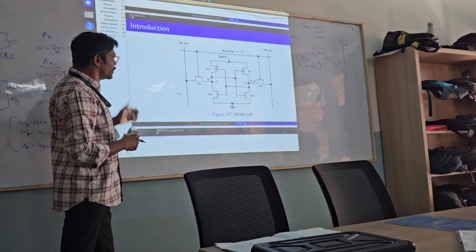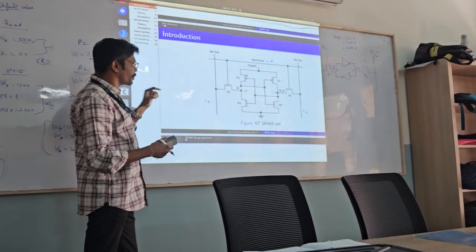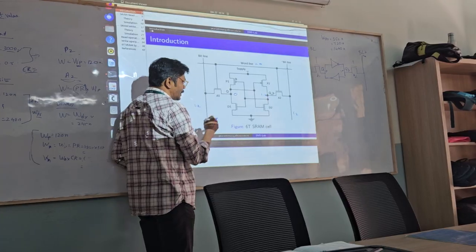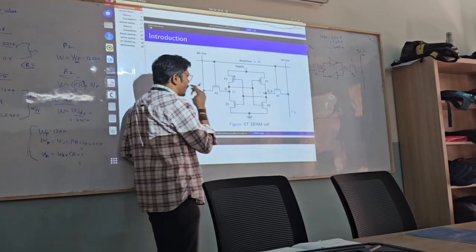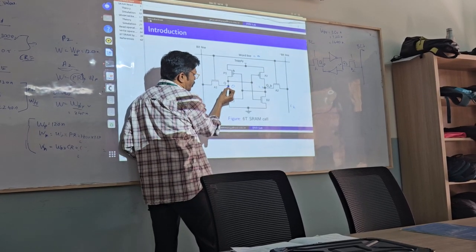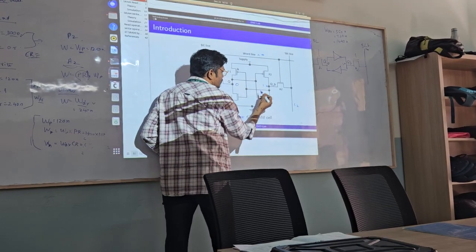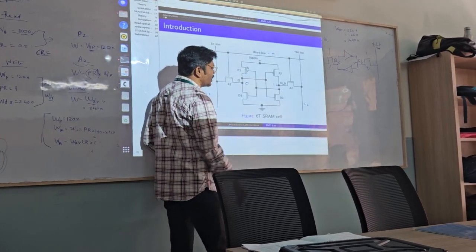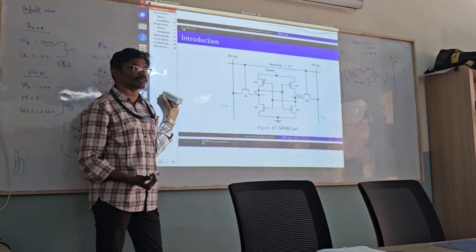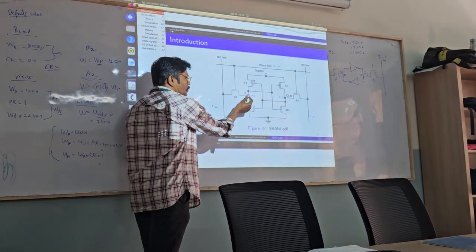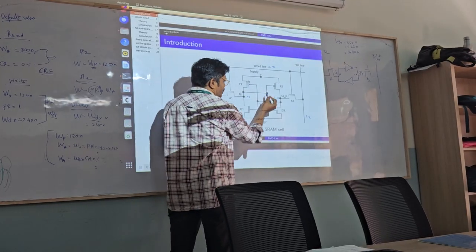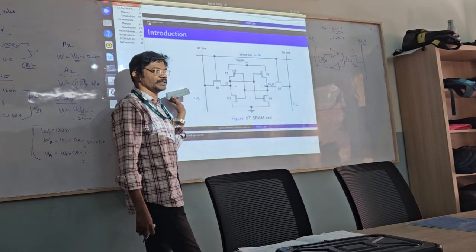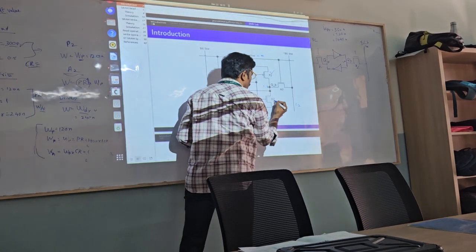Okay. So now we are going to perform a read operation, but before that, based on this initial condition, let us try to see which transistors are on. Now, as we can see, the node Q drives the second inverter, which is formed by P2 and N2. Among these two transistors, which is on and which is off, when Q is at logic value 0 and is driving the gates of P2 as well as N2? Which one would be on in this case? P2 is on, yeah, so P2 is on while this one is off.